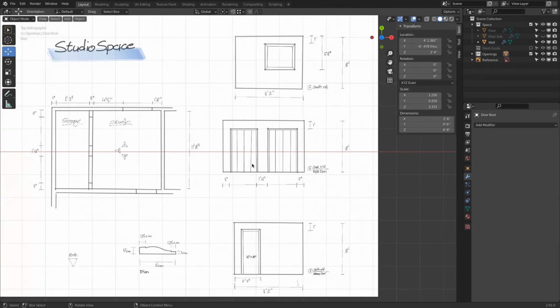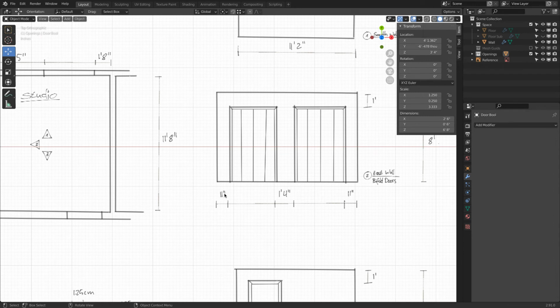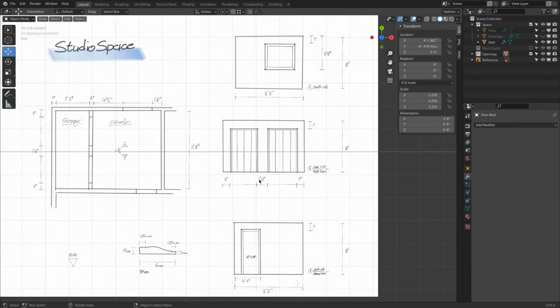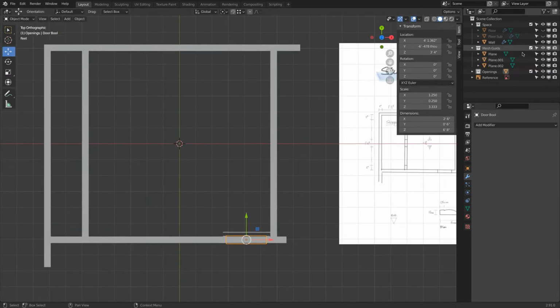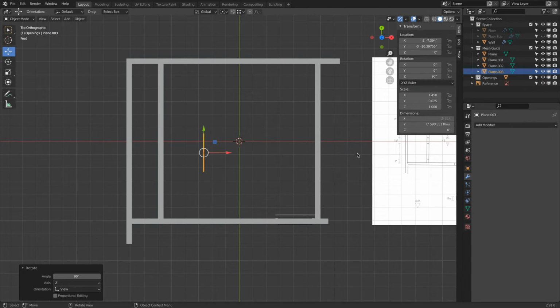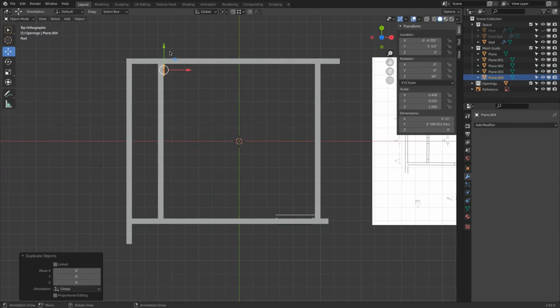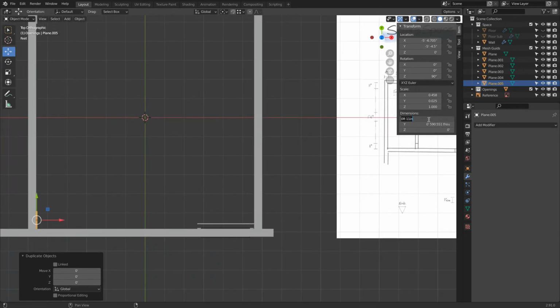Very good. Okay, so how can we do, for example, this very quickly? So we have 11 feet and 1 foot and 4 inches. So mesh guides. I'll make a copy of this here. Then I can rotate this and say, 11 feet. Very good. Snap it to there, bring it back, Shift D, bring one to there, Shift D, and then this is 1 foot 4 inches.